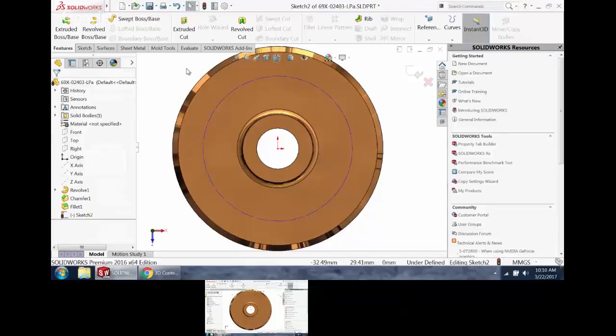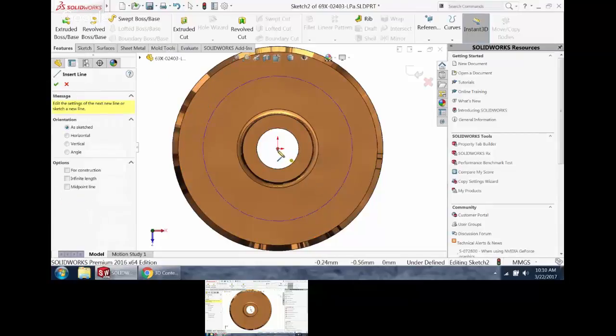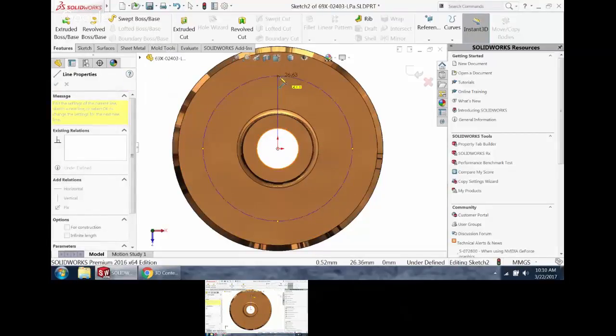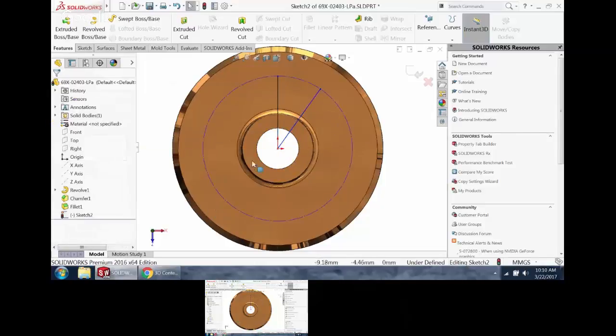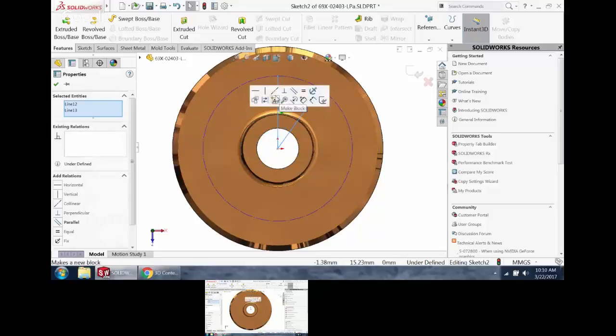Okay, so let's get back into lines. I'll go this way with my mouse gestures, start drawing some lines. Do that drag and drop option. Select all these. There's that pop-up again. So anytime you select things, it's context sensitive. Because I picked 2 lines, I've got choices like perpendicular, parallel, equal distance. If I'd only picked 1 line, I would have just had horizontal or vertical for a choice.